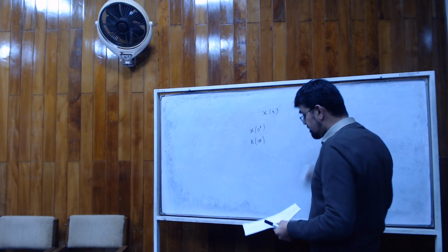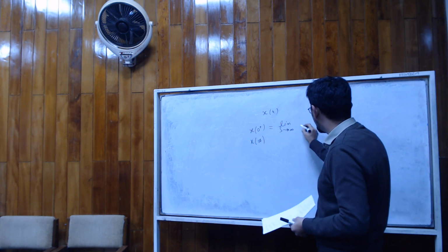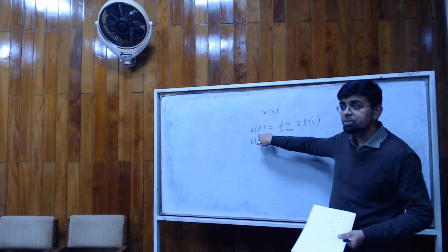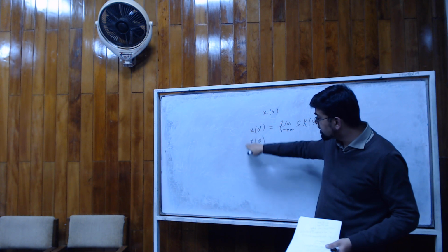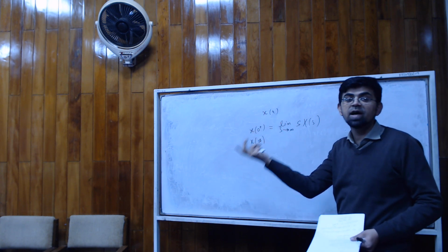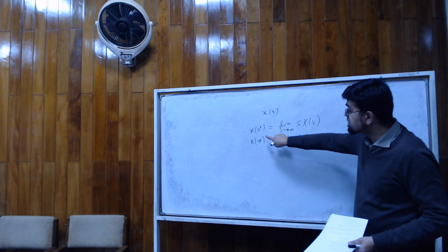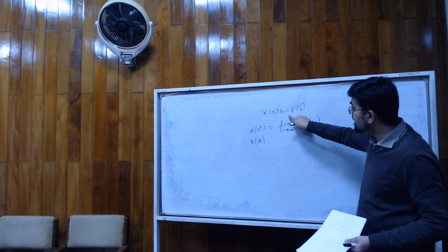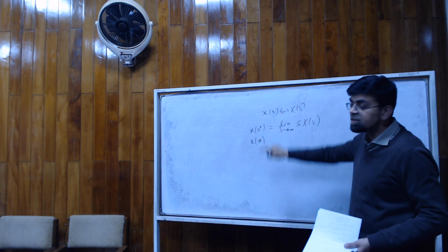Often when we are working with the frequency domain, it actually helps to know this rule: sXs. If you want to find the initial value of a function in time, there is another way to do it. You may say, okay, why not do it here? Often it is not possible to get these. The function may be defined in such a way that it's not easy. So what you do, you take it in the Laplace domain and find it there. So what does that say? It says if you want to find this, all you have to do is take the Laplace transform of your original function. Maybe you already have it in some form. Multiply the Laplace transform with s and then set the limit s goes to infinity. If this limit exists, that will be the initial value.